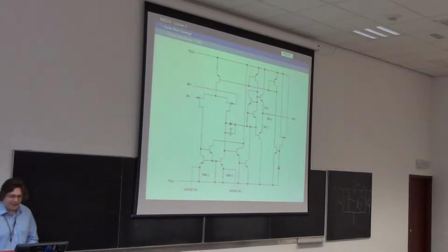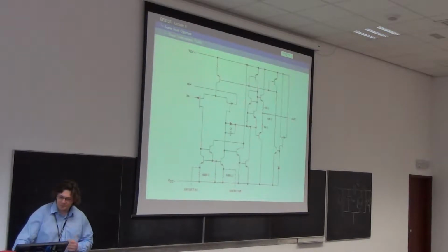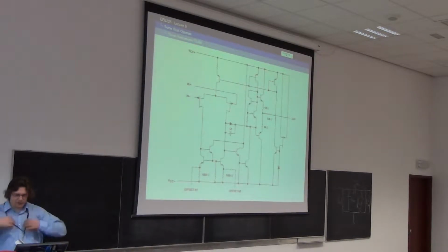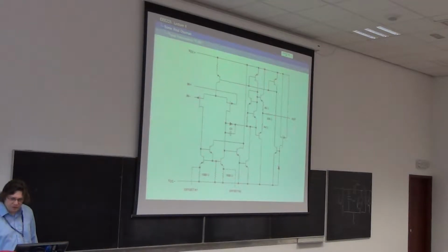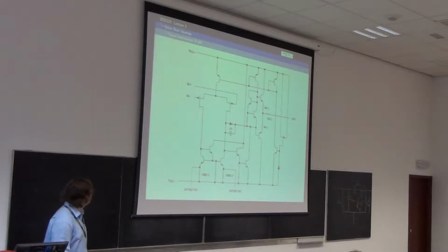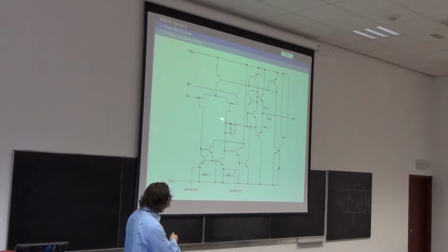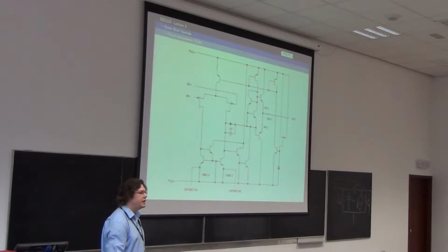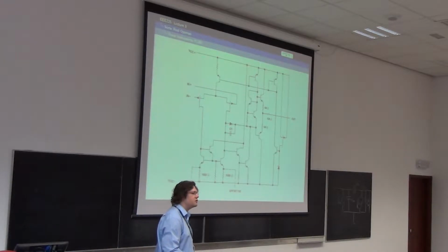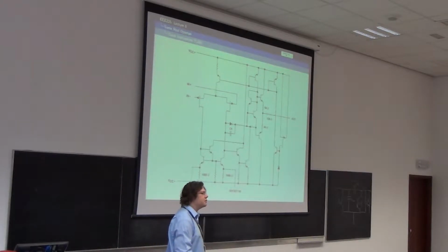Okay. In that case, let's have a look at some op amps. This one we saw briefly yesterday, so I'll zip through it again if you weren't here. We have a differential input stage made of 2 JFETs. We have an enormous current source. If you've got a bipolar op amp and you find a JFET in it and it's not in the input stage, there's a pretty good chance that it's there to form a current source.